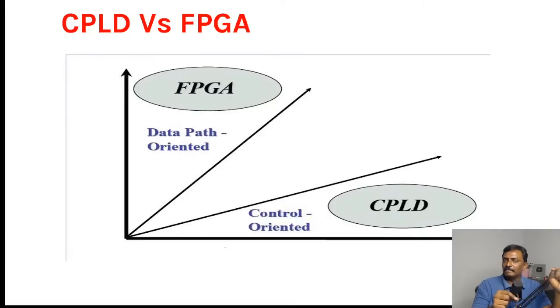Whereas CPLD is just like a tailor-made shirt. You could customize the IO pins. The IO pins will be general IO pins. If you want a serial communication pin like UART, you could use it as that. If you want it as an SPI pin, the Serial Peripheral Interface, or I2C communication, you could have that, and you could have any number of UARTs, 2, 3 or 4 UARTs. You can customize the architecture inside the CPLD, whereas in microcontrollers, you cannot customize the architecture.